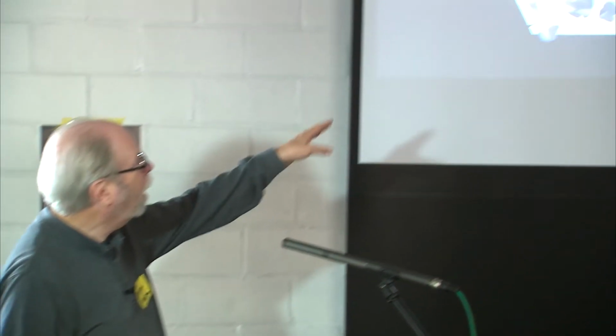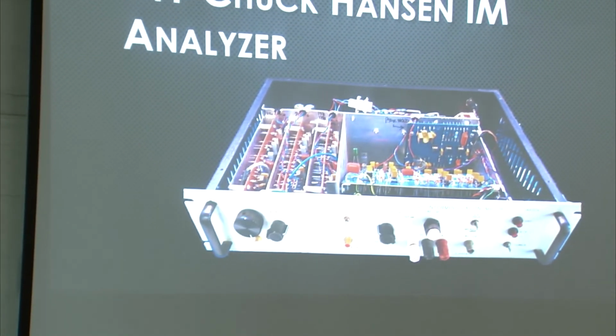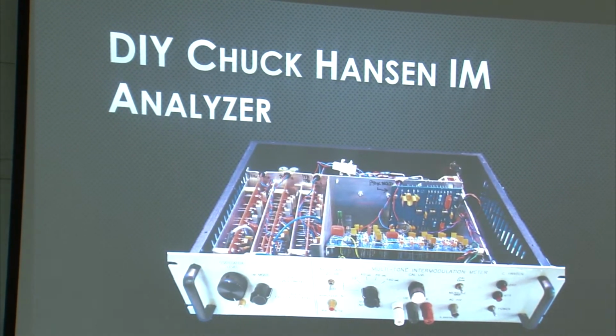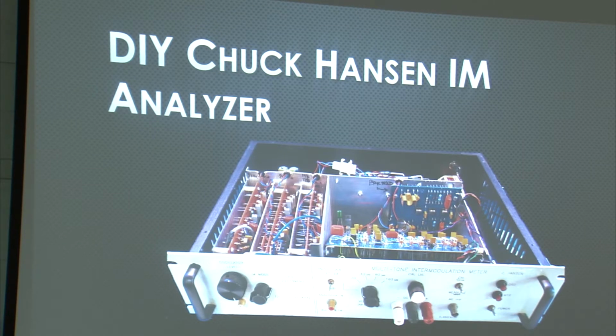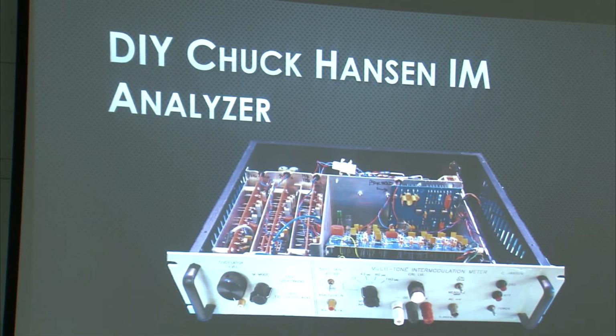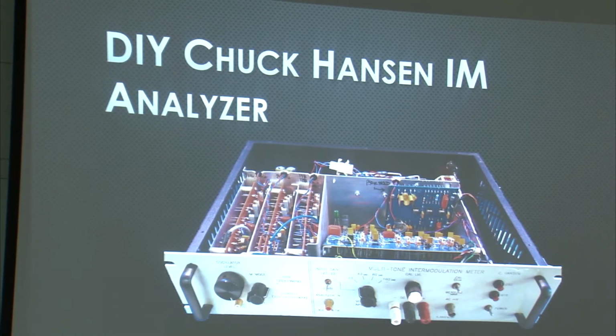Here is an IM analyzer, and this is another example of the kind of task it has been in the past if you want to build a high-performance analyzer and you want to build it yourself. This instrument is quite good. Actually, its residual is about minus 120 dB, but that's all hand-wired. It's a huge project. If anybody's interested, I have all the documentation I'll share, but it'd probably take you 6 months to successfully build it.